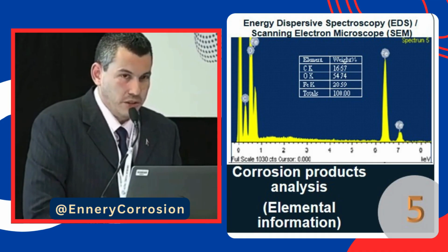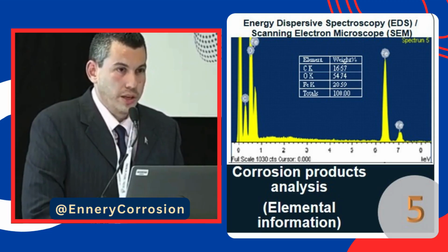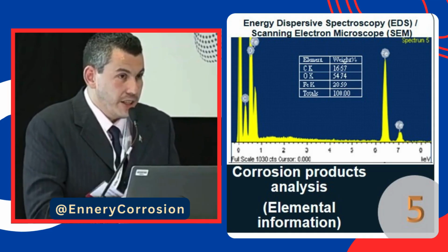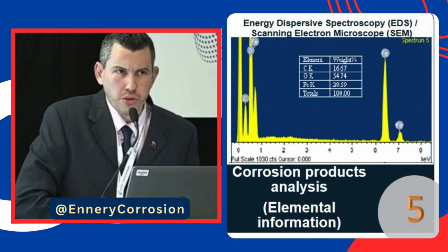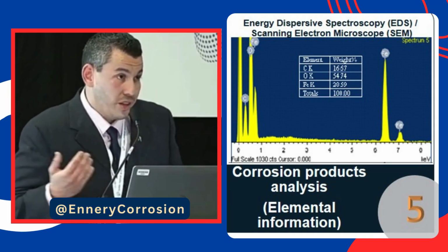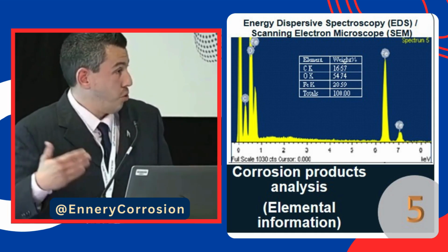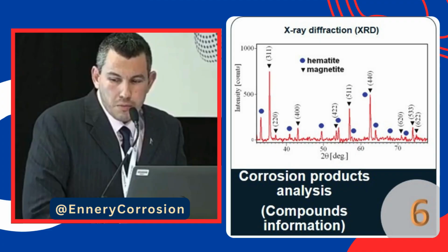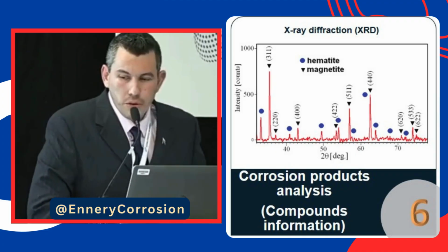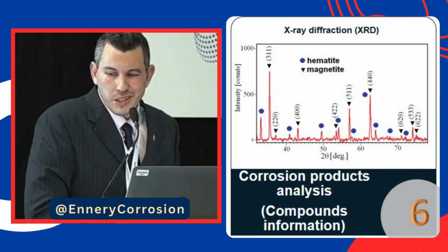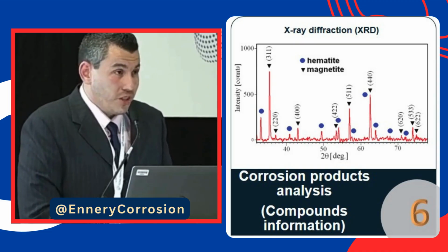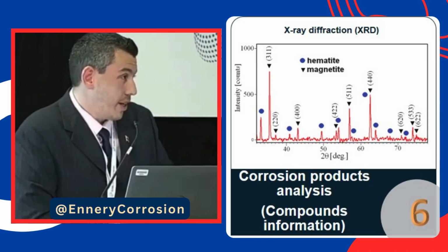It could be a risk for your safety, could be a sign that maybe in one injection pump you have a seal that is broken, and then you have oxygen coming into your system. So this is one of the advantages of using corrosion coupons, not only for mass loss analysis. And maybe not applicable for our daily business, but corrosion products can also be analyzed in more detail.